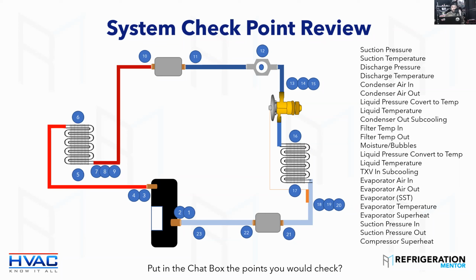Since you said insulation breaking and deteriorating, I want to give a tip to everybody. I've been changing a lot of insulation myself lately on refrigerant lines because of that. After so many years, the UV and the Armaflex just starts to flake, and you can touch it and it falls apart. I've been starting to replace it with K-Flex Titan.